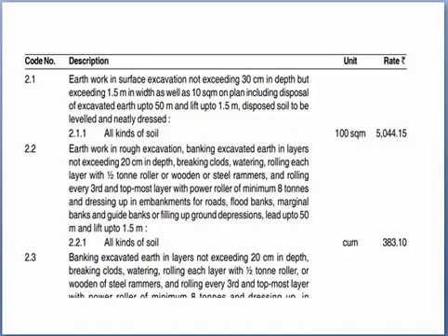So the unit for the surface excavation will be the square meter, and the rate 5044.15 is against the unit of 100 square meters. Otherwise, if we talk about the earthworks, the unit is cubic meter. But because this item is of the surface excavation, we will consider the unit as 100 square meters. So the items which include the surface excavation, the unit is square meter, and the items otherwise related to the excavation works, the unit will be cubic meter. So you need to be very careful while attempting the questions. Either the earthwork in excavation is surface or it is the normal excavation.